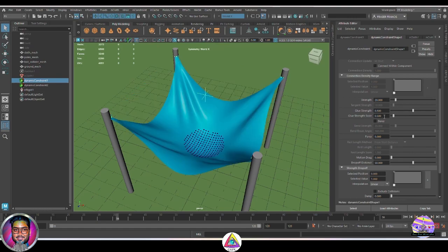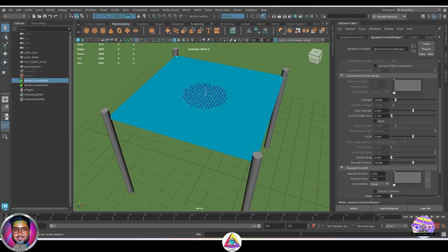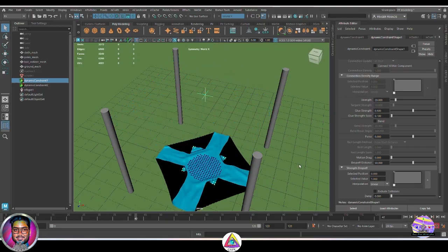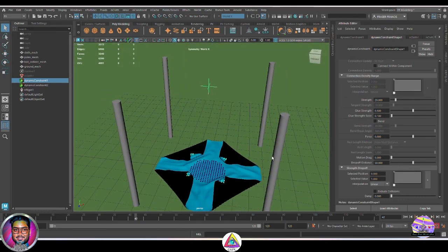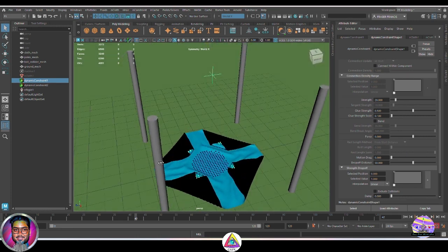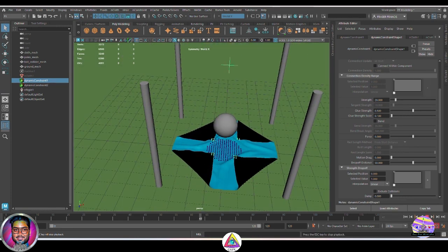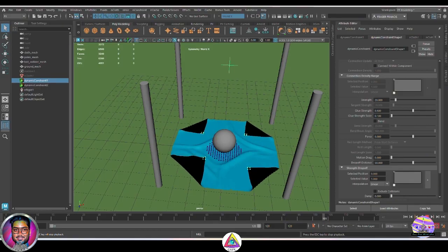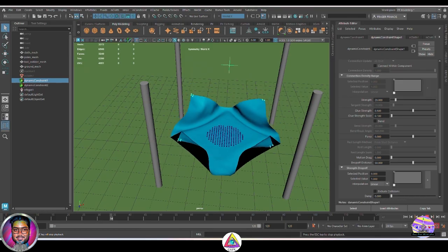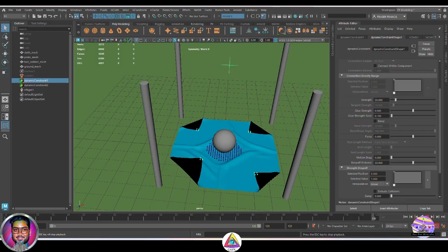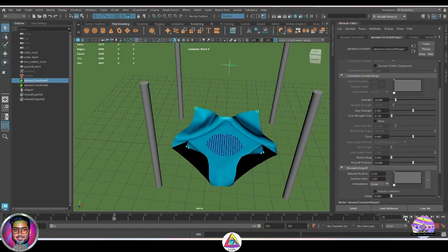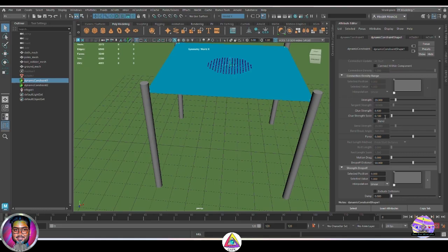So it is by default 0.5. So let's make it a little less and go with 0.1 and see what happens. As we see, without the interaction of the ball, when we reduce the glue scale to 0.1, the entire cloth falls down under gravity. And if I just run the simulation, it will very naturally, like a rubber sheet, a kind of thin sheet, fold and unfold with the motion and the stickiness it has, right? So that's what is happening with the glue strength scale now.